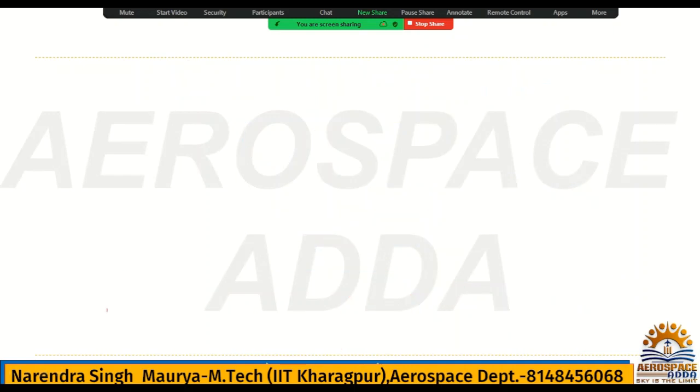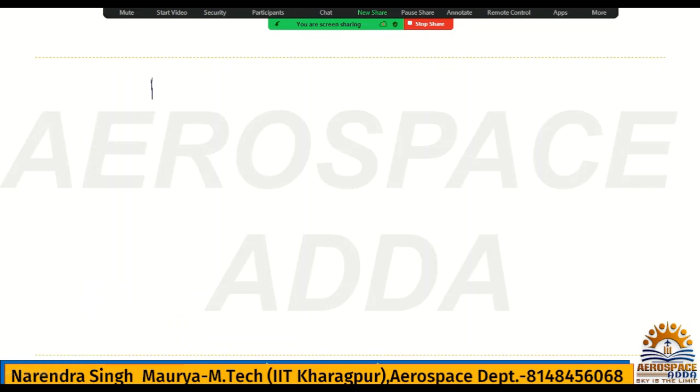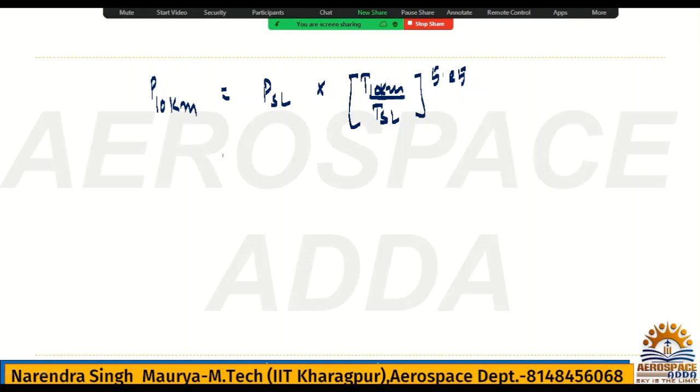So P at 10 kilometer can be written as P at sea level into T at 10 kilometer by T at sea level to the power 5.25. What is the sea level pressure?